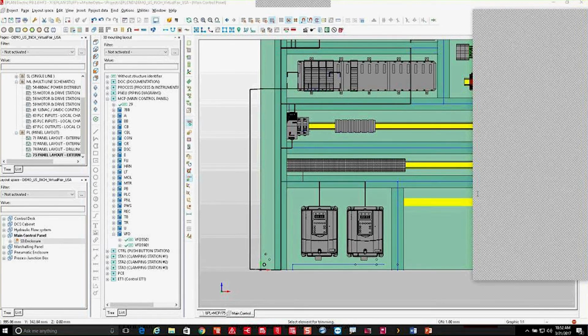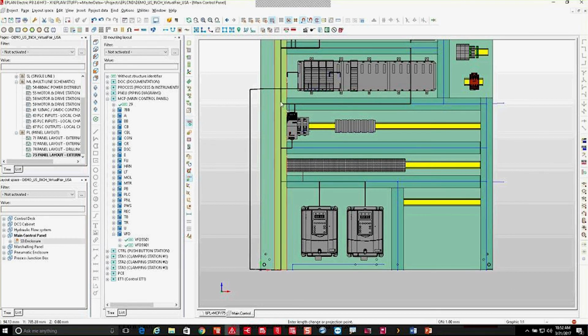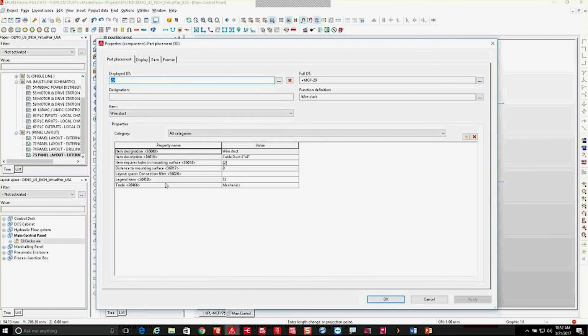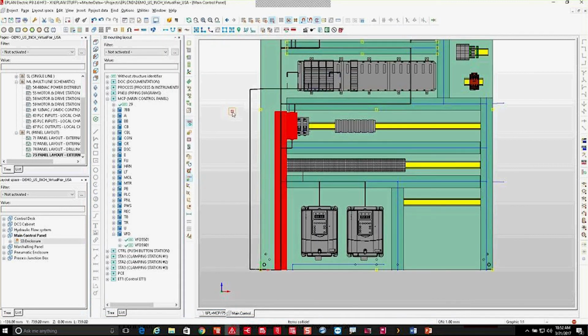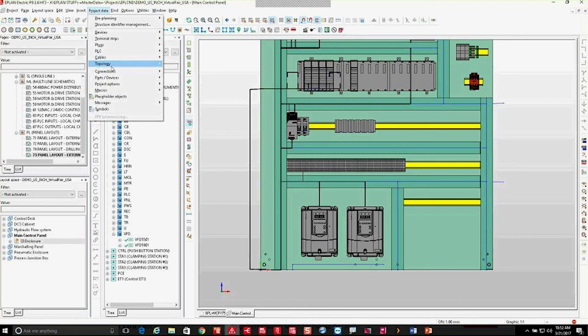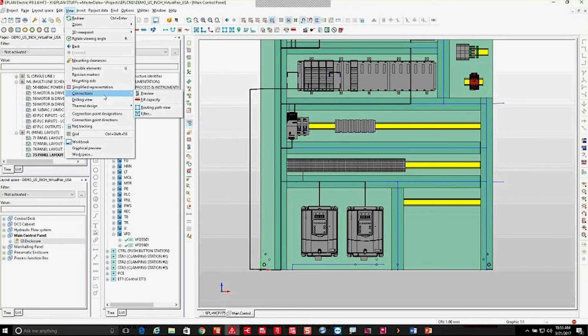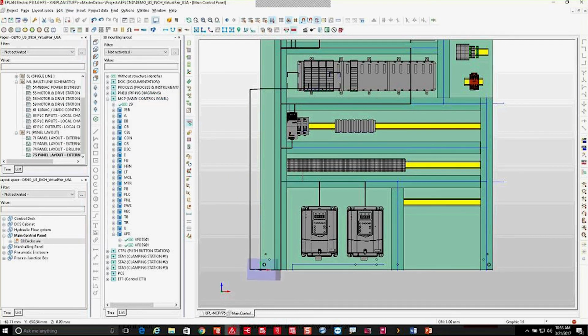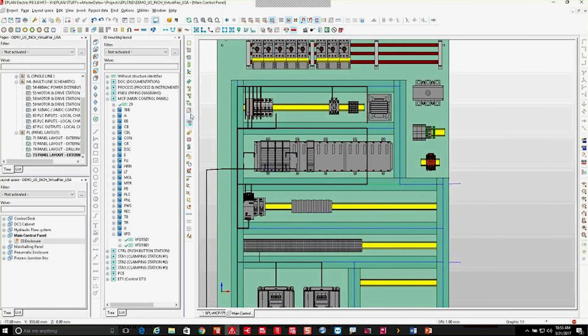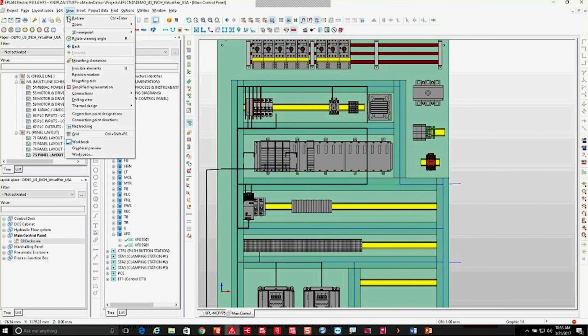So yes, of course, the fill capacity that we have here is if you select the wire duct, you can specify based on the cross-section diameter of this wire duct, you can tell the system to warn you at certain levels. And once you've specified that information, if we go under View, we have the capability under connections to show the fill capacity. And of course, depending on the different available space, it will let me know. Also, I can tell the system to calculate that fill capacity level.